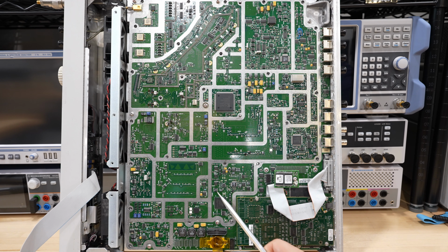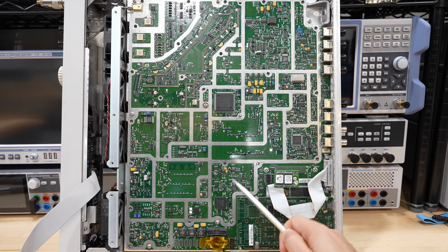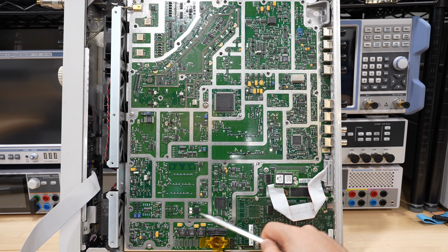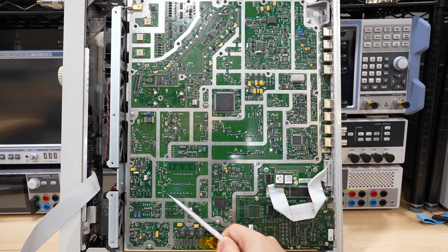There's also a couple of additional hints, because over here there are ADC and DACs, which are responsible for the FM modulation. We saw that in the block diagram as well, feeding it directly into the loop. It all has to be within proximity. So the loop of the PLL is essentially this path over here. So we have to pay attention to this. And there's a couple of other bandpass filters you can see with switches in between them.